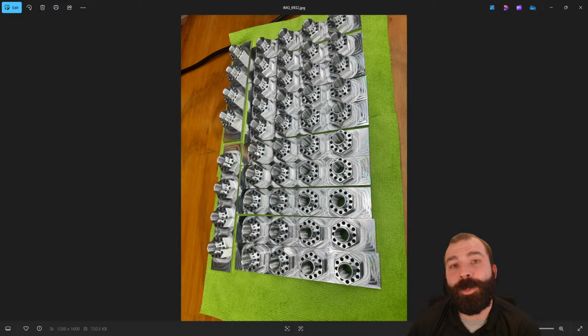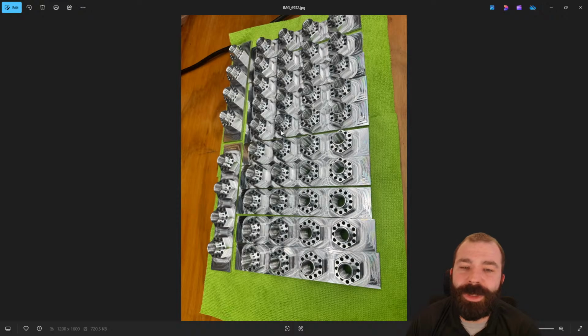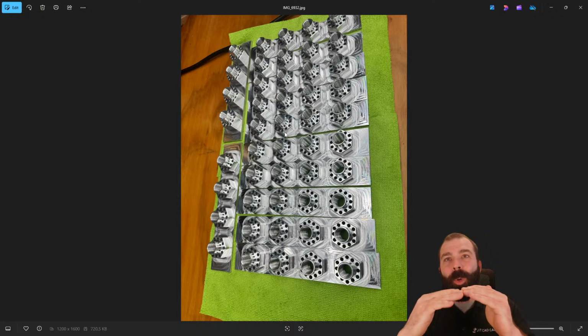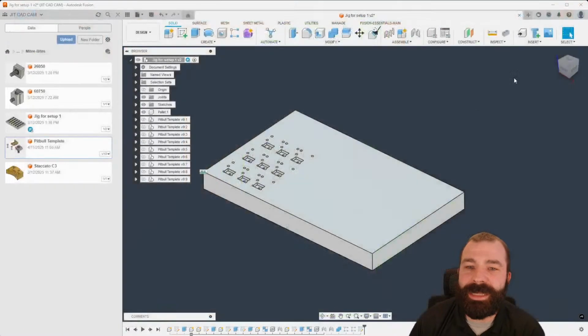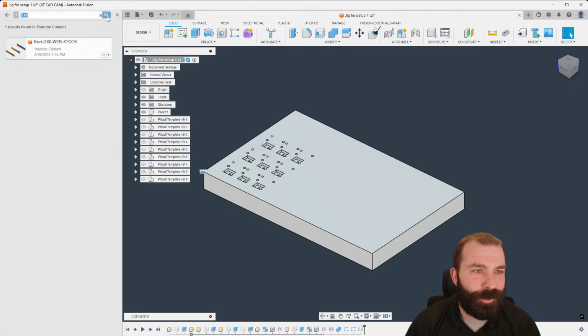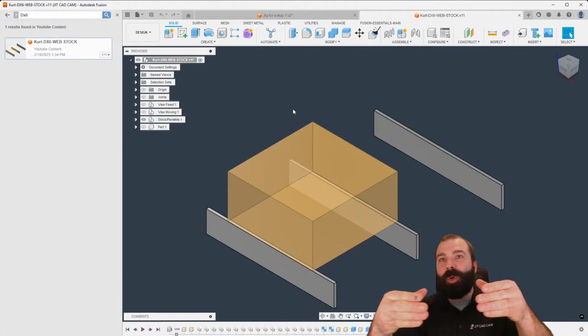This is something I would warn a lot of you about if you were to do something with soft jaws, right? When you relieve a lot of material around parts like this, it tends to bow the actual material. So if you flip this and put it in like a DX6 vise, which of course I closed out, let's get that pulled back up, your clamping on a DX6 vise is horizontal.